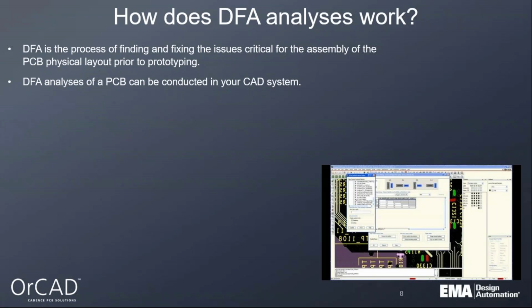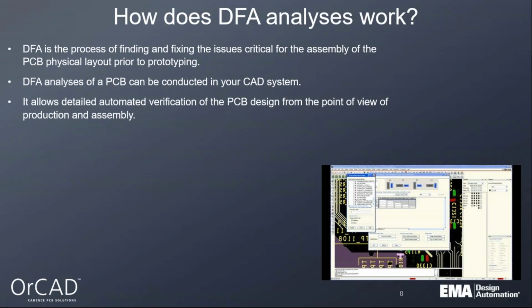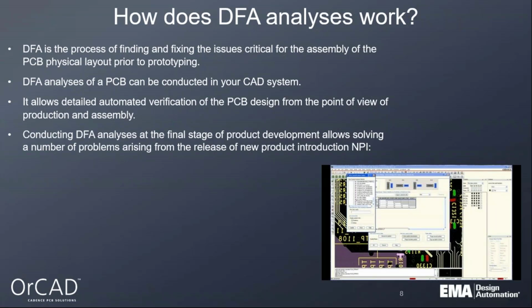Most CAD systems today, the higher priced ones, not the Eagles and the DipTraces and things like that, but the higher priced tools are going to have some kind of DFA analysis built right into the tools. It's going to allow you detailed automated verification of your design from the point of view of the production assembly house. So this is a good way to get an idea of what's going to happen when your board is being assembled. So you're going to want to be able to abide by these guidelines that are available.